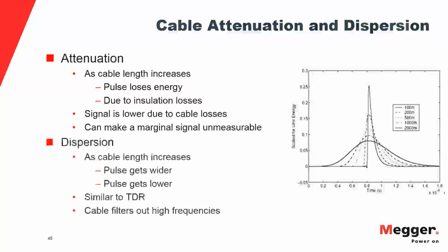We also have our TDS 40 and 60, which does testing up to 40 or 60 kV. And this unit has damped AC and cosine rectangular built in. It's suitable for PD diagnostics and VLF withstand testing. We have a unit called the TDM 4540, which combines the best of both of these. So we have damped AC, cosine rectangular, and sinusoidal all in one unit. This tests up to 45 kV peak, and this is suitable for all testing, PD, tan delta, VLF withstand testing,